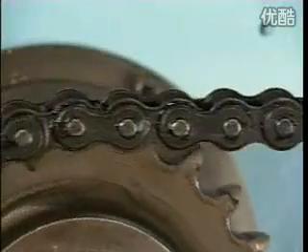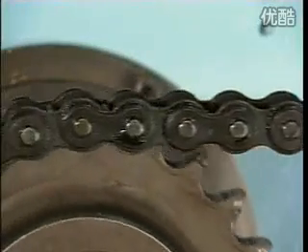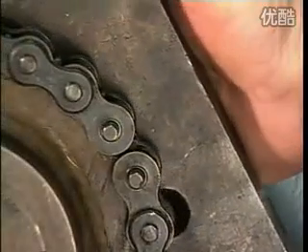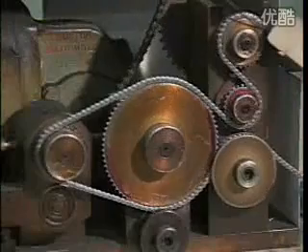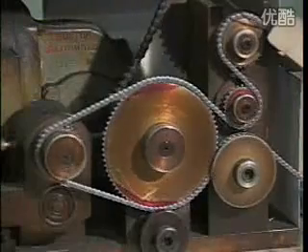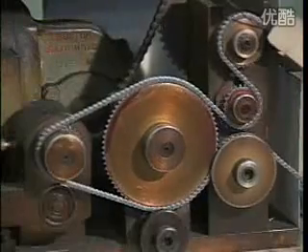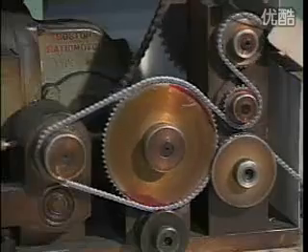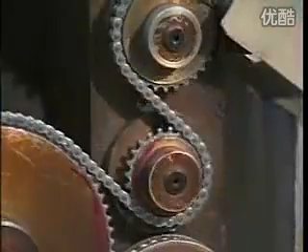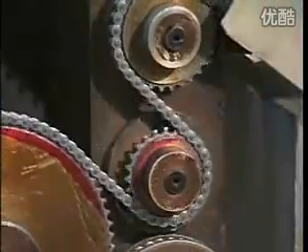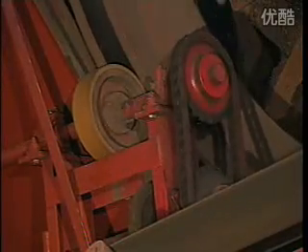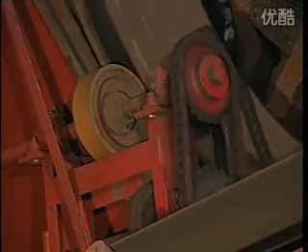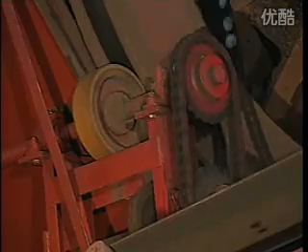The program will explain why chain is so widely used, detail its advantages, and show how to identify and select the correct size and style of chain. The modern chain drive consists of a driving sprocket, one or more driven sprockets, and an endless chain with hinged joints. The chain transmits power from one sprocket to another. The chain meshes with the sprocket teeth and maintains a constant positive speed ratio between the driving and driven components.